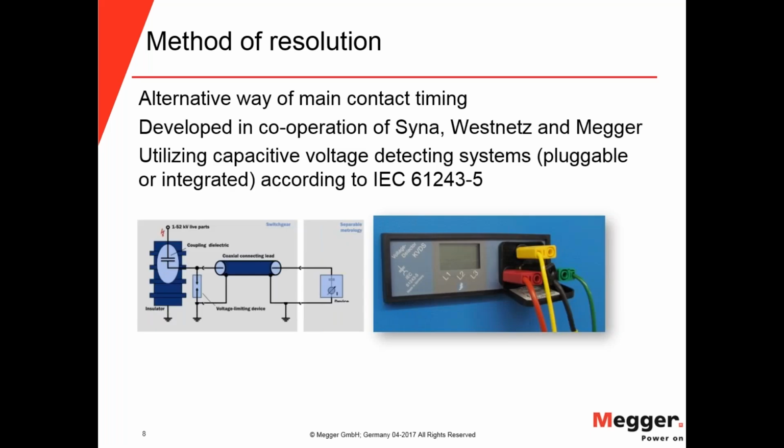And the principle is to utilize the capacitive voltage detecting system named VDS, according to this IEC standard that describes this interface.